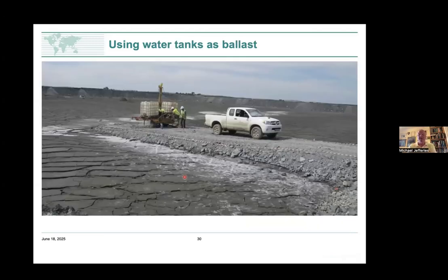And here's another example. Rather than using a hydraulic excavator, we've used tanks which they have chemicals on a mine. This is a tank we've had chemicals delivered in. We've now just filled it up with water and put it on a platform. So we're using water ballast to give us the reaction so we can push the CPT into the ground. And we're out onto our tailings, very loose tailings, and we're managing to do that with only about 0.5 meter of crushed rock to get out onto the tailings.